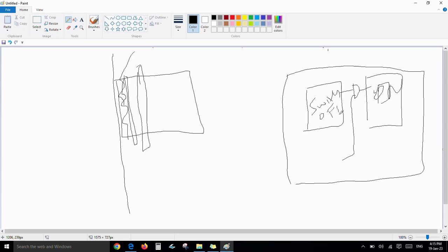Whenever this is off, this needs to be always on. But how do I turn it on? Based on some switching given here, we will be placing an OR gate here. Even if it is off, if I am giving one signal, this block is going to turn on. That is what will be going on. So this cell is an isolation cell.